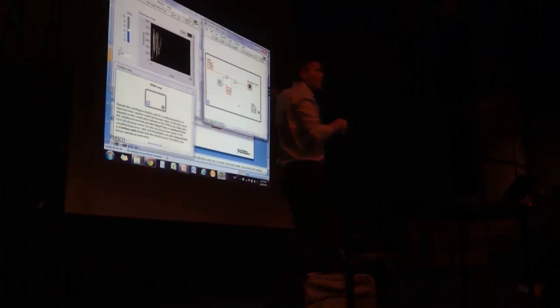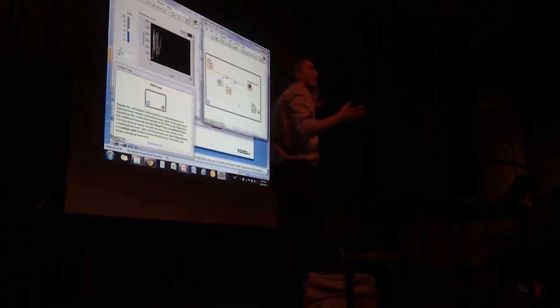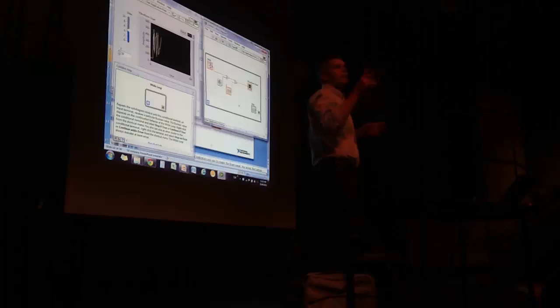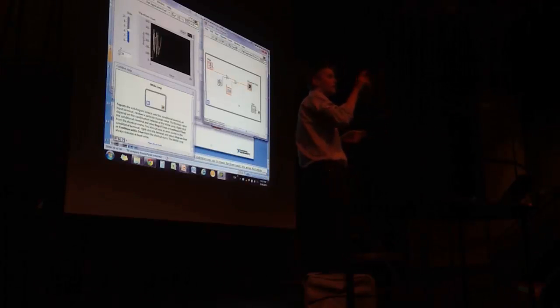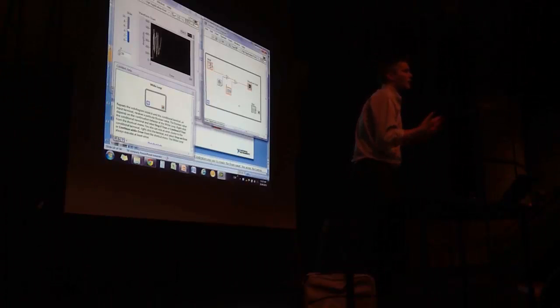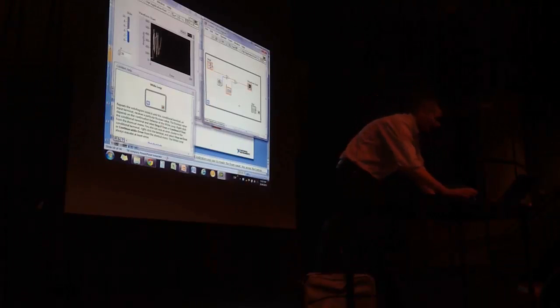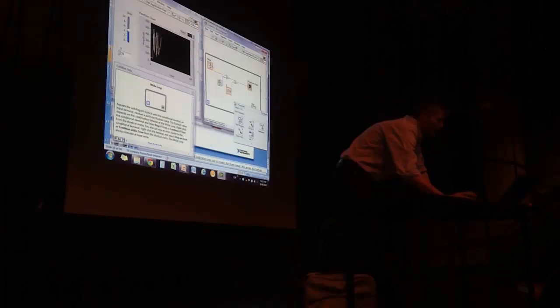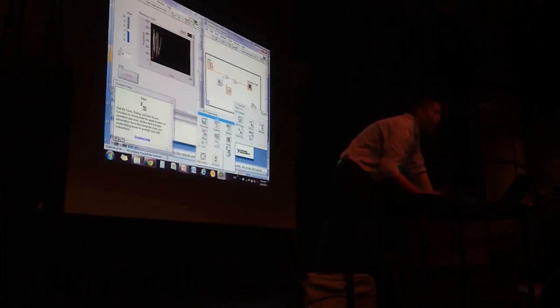But I want to generate, for example, only 2 samples a second. So every second I want to have 2 new samples. So every 500 milliseconds I want to generate a new sample. Therefore you have here on the programming side timing functions.